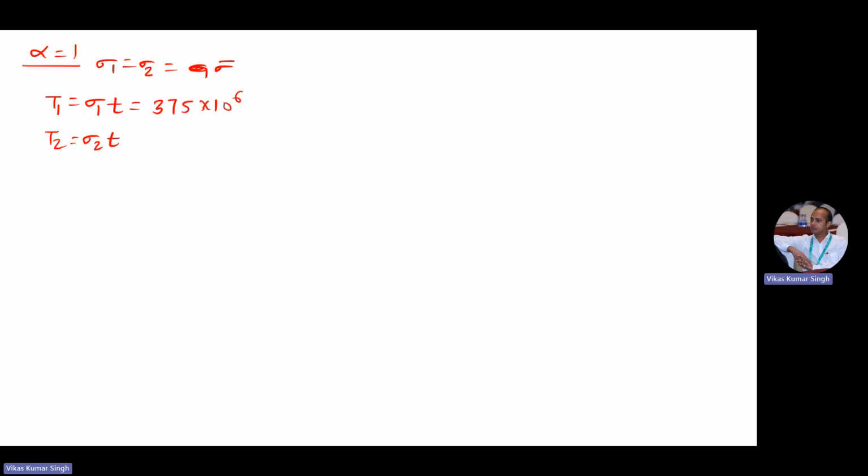So I am writing in SI unit. Okay. And into thickness is 0.626. This is in mm, so we can write it in meter now. And now if we are finding, this value is going to be 236 kilonewton per meter. This is the traction, or you can say the tension. The principal tension is T1 or T2, both the values are same.